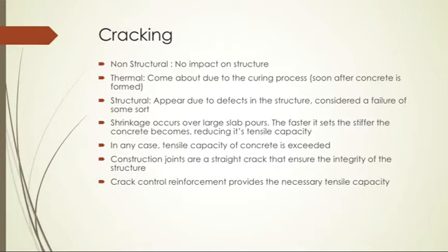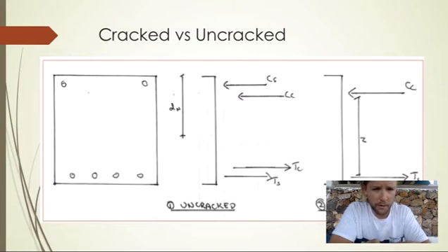So that's why we include construction joints in the slabs, to minimise the shrinkage cracks. And so crack control reinforcement, which we'll get into soon, is provided to give the concrete the tensile capacity to reduce the cracking of the concrete.